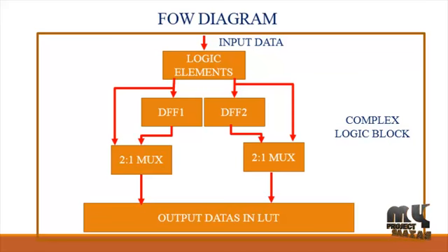And next, the output is fed into the D flip-flop. One of the main disadvantages of the basic SR flip-flop, a bistable circuit, is that the indeterminate input condition, where set equals logic 0 and reset equals logic 0, is a forbidden condition. This state will force both outputs to be at logic 1, overriding the feedback latching action, and whichever input goes to logic level 1 first will lose control, while the other input still at logic 0 controls the resulting state of the latch. But in order to prevent this from happening, an inverter can be connected between the set and reset inputs to produce another type of flip-flop called a D flip-flop.